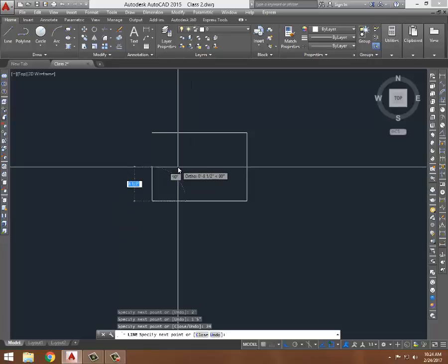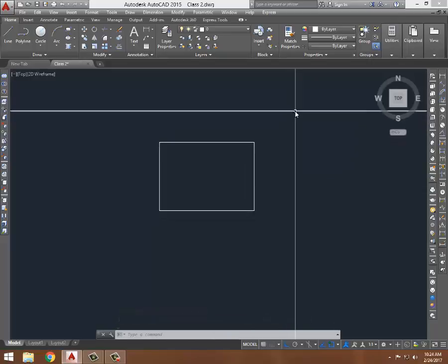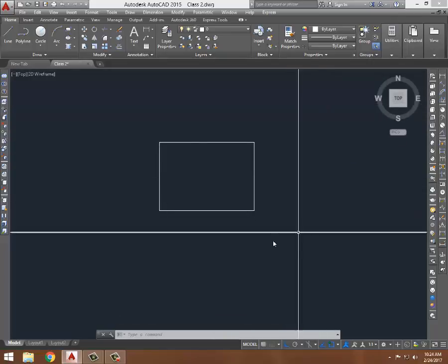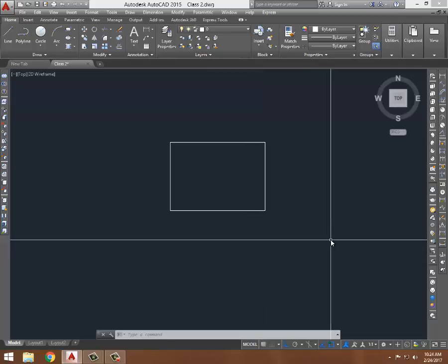Now I want to close this shape. I do not need to provide 1 feet and 5 inch again. I just press C for close and enter. So my box is complete. I want you guys just to remember, we can use inches, we can use feet and inches, and we can use only feet if we want. So that's how I'm going to close the topic about line.